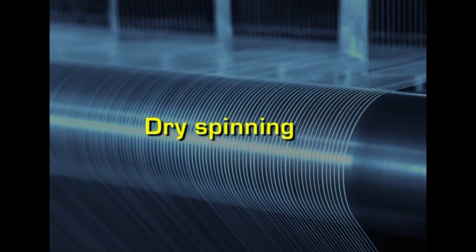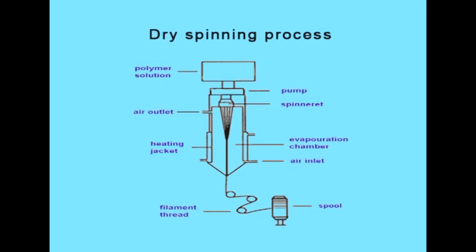The second method of chemical spinning is dry spinning. When the polymer is not of the melting or thermoplastic type, we have to see whether there is any volatile solvent that is applicable to that particular polymer. If so, then we can go for dry spinning. This is also a simple method wherein the polymer is dissolved in a solvent, extruded through the holes of the spinneret, and then it gets solidified through evaporation of the solvent.